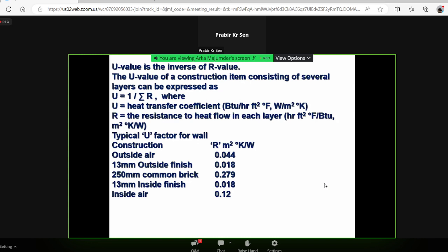Outside air is turbulent because there is continuously wind flow. So the turbulent boundary layer has lesser resistance to heat. That means heat transfer is more in the turbulent boundary layer. That's why we have made the turbulent boundary layer for cooling coil fins.